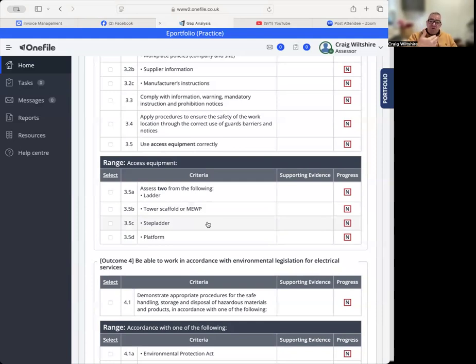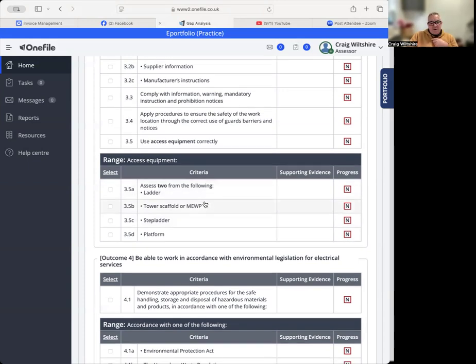We're going to go through the do's and don'ts, the maximum weights, the minimum weights. What step can you go up to? Right? How do you put tools on the ladder? Is there a place on the top to put your tools? Do you have to have your tools in a belt if there's not? How do you use a ladder correctly? Right? 3 points of contact, stepping up the ladder, not leaning over. That's the type of examples we're looking for, you checking and using access equipment correctly, okay?